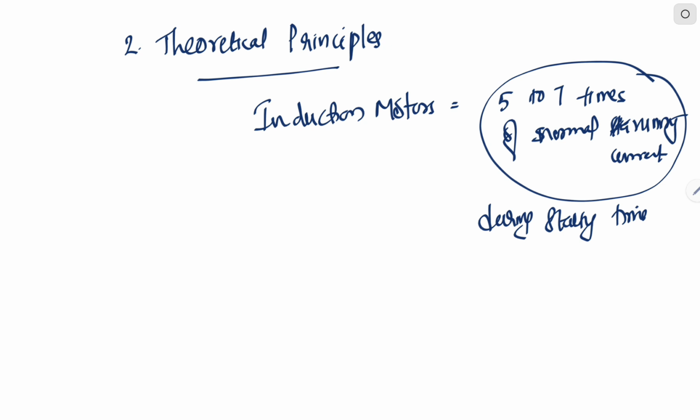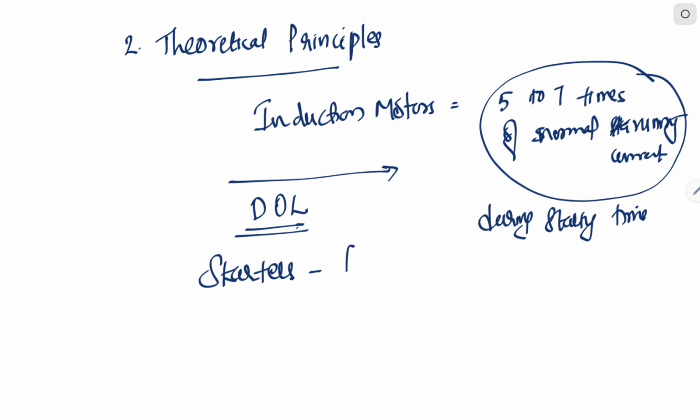So, for electrical designs which consist of so many induction motors, small capacity or bigger capacity, for each type of motor we have to follow these theoretical principles that we studied during our college time. Or just keep in mind that induction motors will take 5 to 7 times the normal running current while starting. So we have to use starters for induction motors.